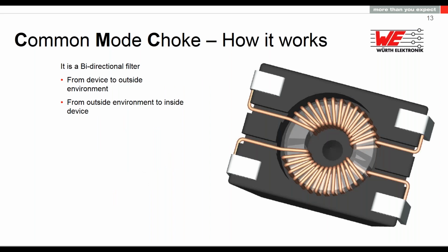Now, what is happening in a common mode choke? A common mode choke is normally wound, I would say 99.9% of the time, on a toroidal or something like a frame core, which is always a magnetic short-circuited core. Now, we have on one side X number of turns wound in one direction, and the same number of turns wound on the other side in the opposite direction. This is called a kind of sector wound inductor for common mode choke.